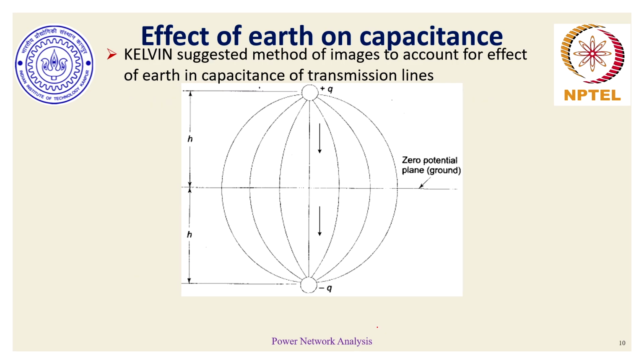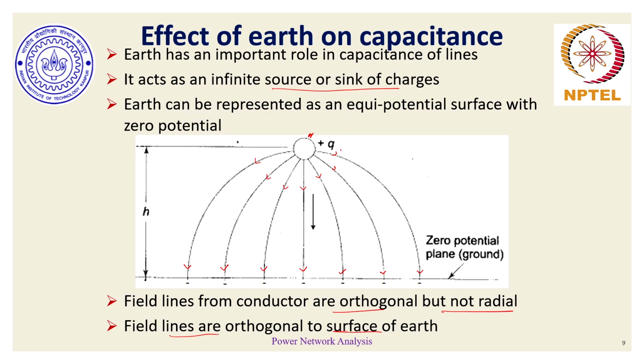So how do we encounter this effect of field lines coming in from the charged body to the earth? Because if the field lines can exist, then we can also mark corresponding orthogonal surfaces, which would turn out to be equipotential surfaces, and the equipotential surface 0 is appearing over here. So a little above over here, the potential difference might be higher and higher till the line whose operating voltage could be of few hundreds of kVs, or let's say 220 kV or 400 kV.